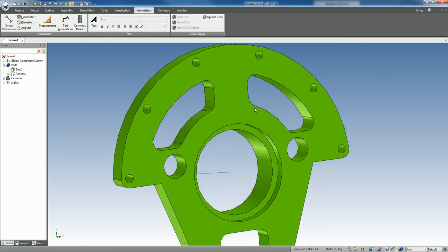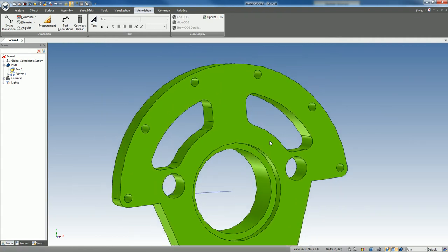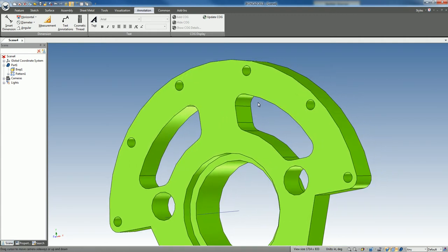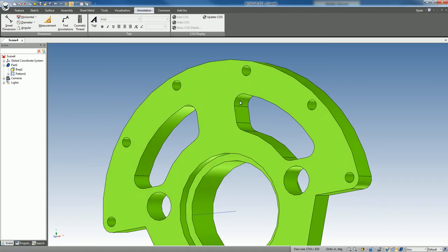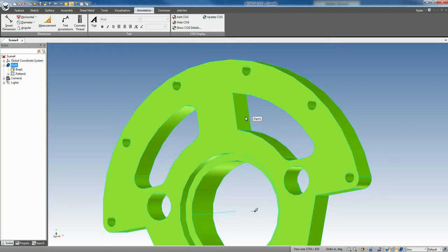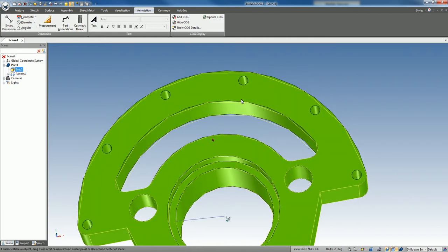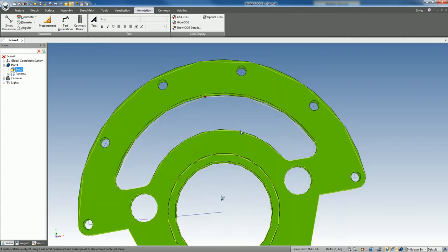Well, let's look at some other geometry. Now, in the demonstration I saw on LinkedIn, it was very interesting that they wanted to change this pattern up here at the top to be just one complete cutout, which you could do in a variety of ways. For example, we don't need these blends here. You can select these blends, defeature the model by just deleting geometry, hit the middle mouse button to continue, take the handle, and pull it all the way through. Notice even though I'm pulling it straight in this case, it knows that there's a curvature on that geometry and pushes it all the way through and maintains that curvature. So you can end up with this as a result.